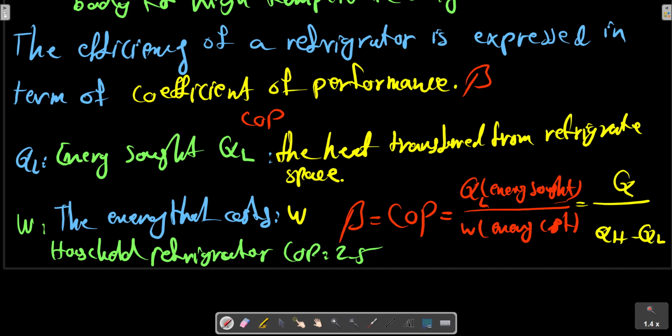A lower cold temperature space or a higher warm temperature space will result in a lower value of COP, as will be seen in the next section. For a heat pump operating over a moderate temperature range, a value of its COP can be about 4, with this value decreasing sharply as the heat pump's operating temperature range broadens.